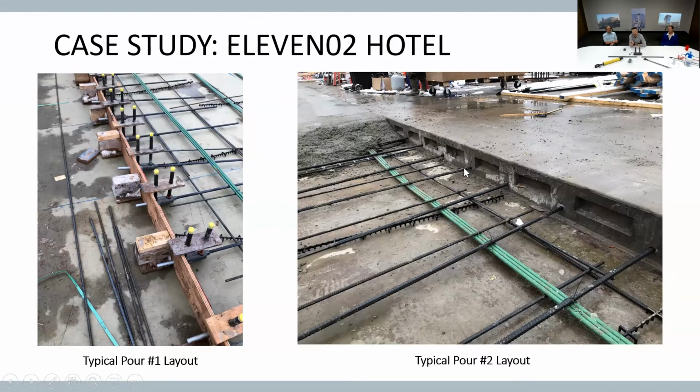One other thing that we do on the edge during the installation process is we spray a debonding agent on the surface of the first pour. It's amazing how well concrete sticks to itself, from what we found. So this is a key part, because it allows this movement to happen, and the bar to shrink and move with the slab.